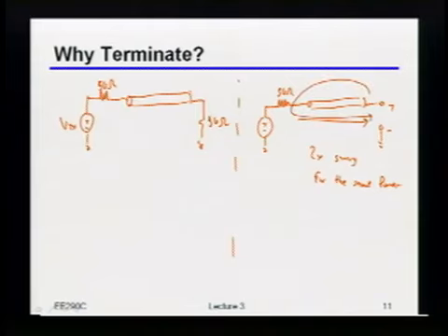Okay? So people like to put terminations on both sides simply to try and keep the signal integrity as high as they can, just to be more robust. Okay? Just to really make sure that you can predict what's going on and ensure that it's going to work the way you want it to. Okay?